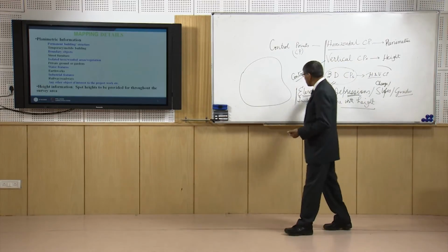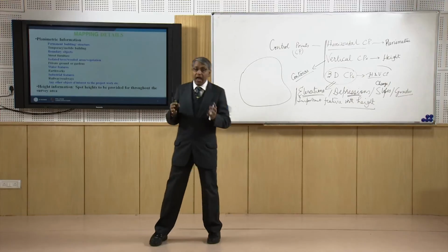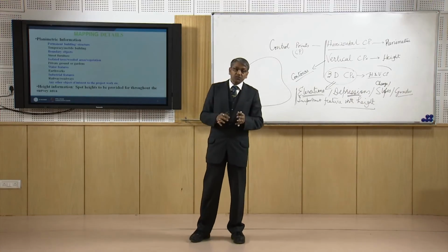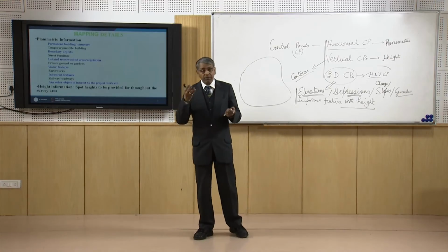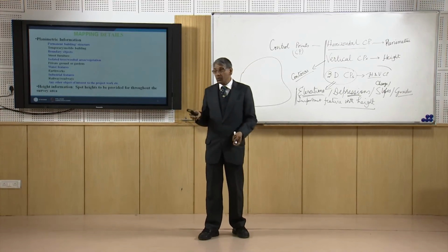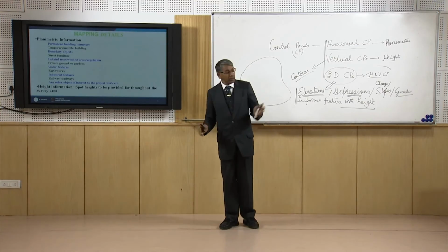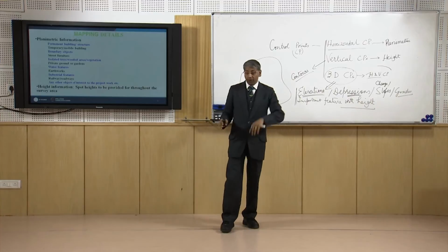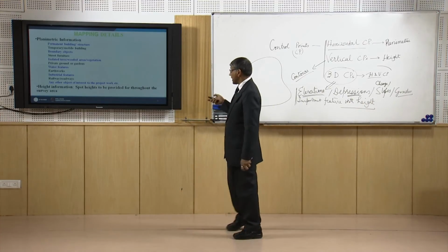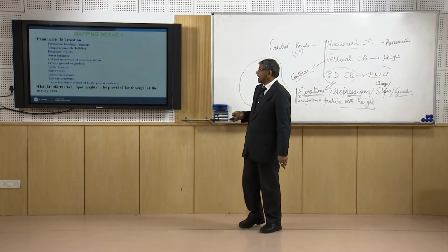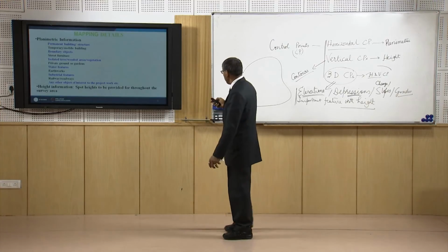So, for all those points, along with some normal points, we should have the spot heights well spread throughout the whole area, because, as I have already discussed in the class on contours, spot heights are required for drawing the contours, and we will need a lot of spot heights to develop the contours. So, we have to take care of that during detailing of maps, and accordingly plot it in the map.